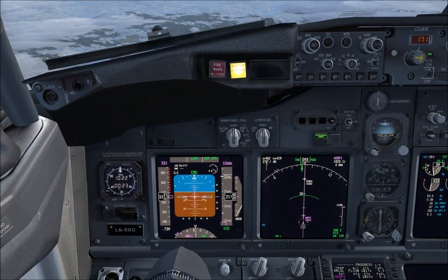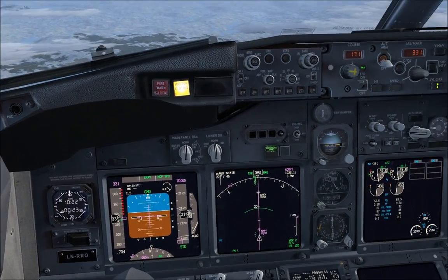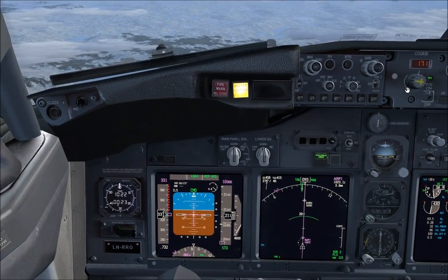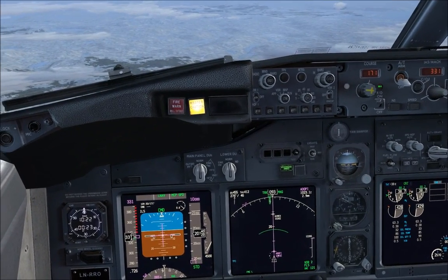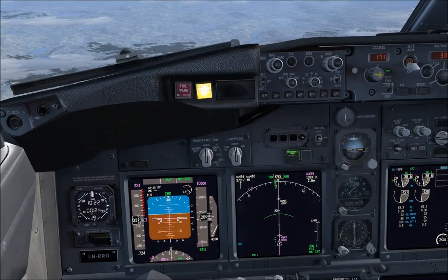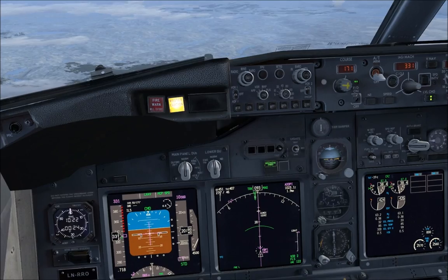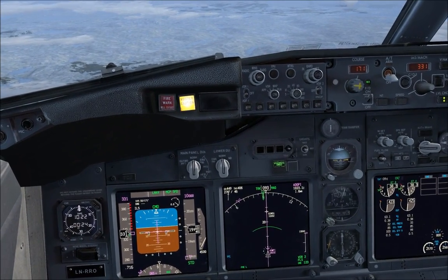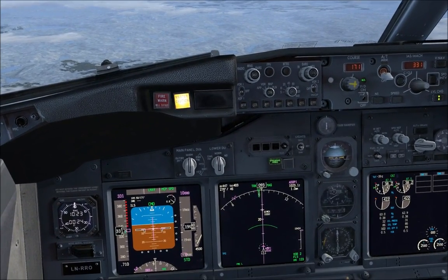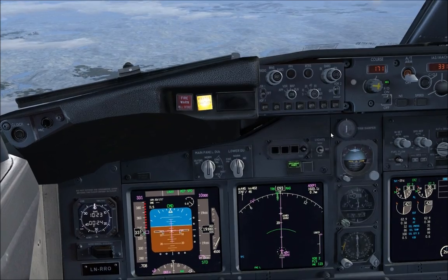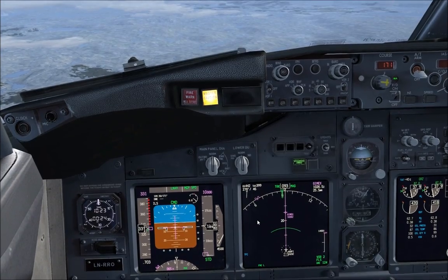I did not announce over the PA to the passengers that we are doing an emergency descent, but I think that is acceptable because we don't have real passengers. However, if you're flying on VATSIM or any other online environment, you would need to inform ATC of your proceedings. This will normally be the duty of the FO, but FS2 Crew can't yet talk to the ATC. The minimum safe altitude for this area is about 8,500, so we're choosing 10,000 as our target altitude.